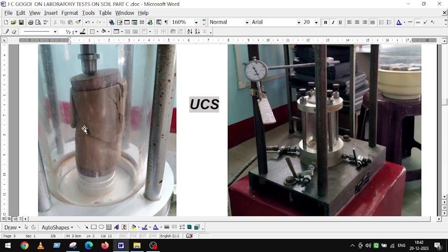You see, it is general shear failure. In general shear failure, the void ratio will generally be less than or around 0.55. In SBC analysis, if we go for detailed analysis, then it will be more than 75% relative density, and the void ratio will be around or less than 0.55.